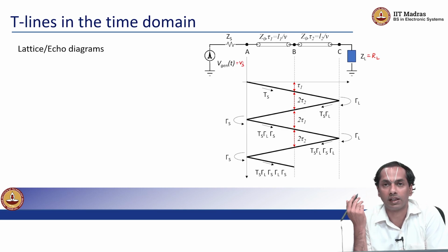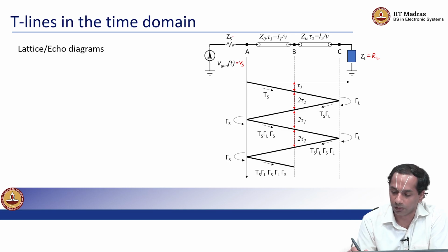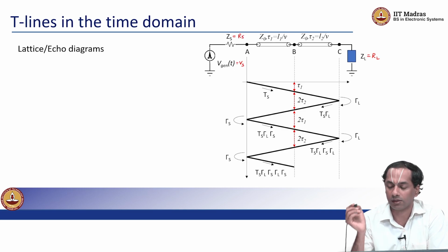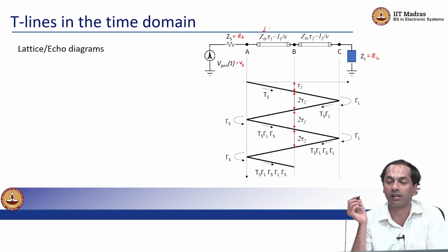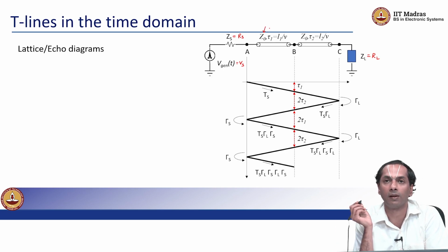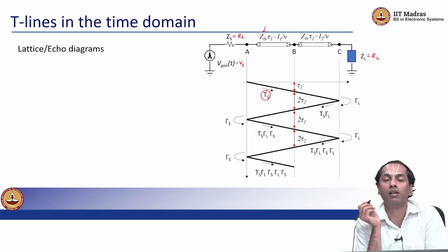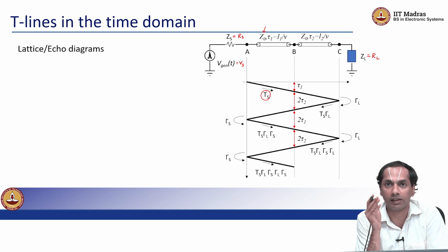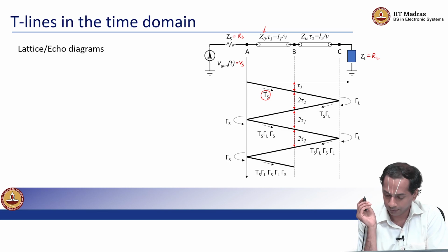That we notice that whatever be the voltage, right, at some particular time t, Vs is a time dependent function based on the value of Rs, the source resistance, and the characteristic impedance of the transmission line. We have a portion of the source voltage Vs that gets launched on the transmission line, right.